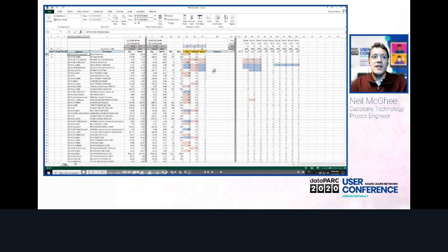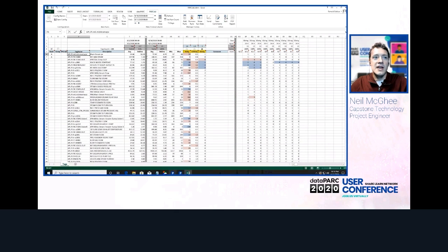If we have identified a specific tag that is unimportant to our analysis, we can mark that tag with an X in the rank column, so that it sorts to the bottom and does not calculate. Alternatively, we could have deleted this tag entirely by highlighting the row and clicking Control Delete. After we click sort again, we can see that it is moved to the bottom.